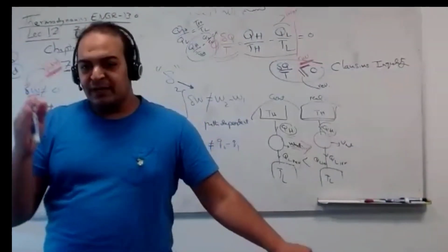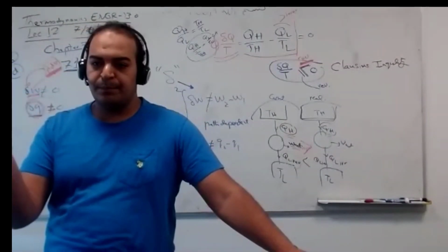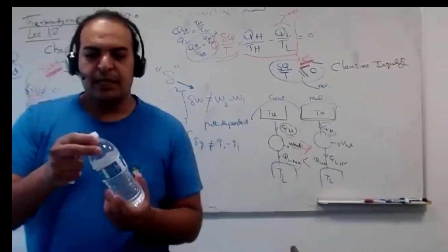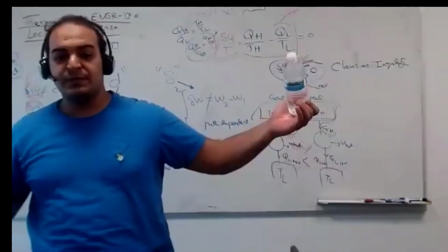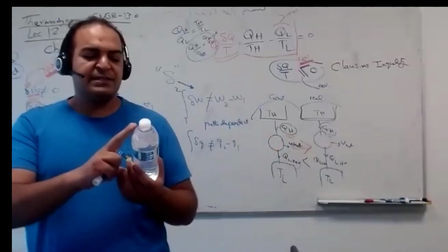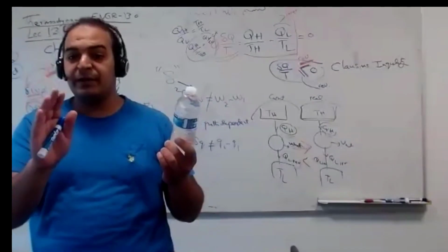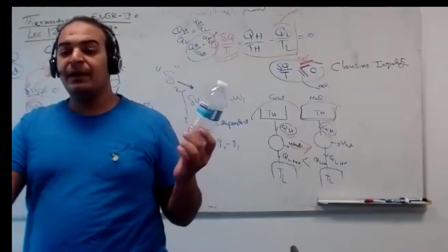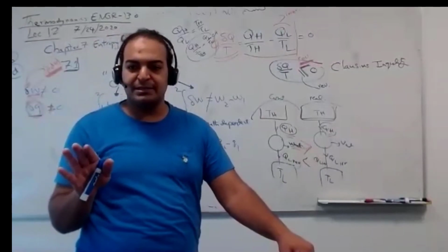The next column, which is VG, is 1.67 meter cube per kilogram. What is this? This water liter, if you heat it up until it becomes totally vapor, the volume becomes almost 2 meter cubes, 1.67 meter cube per kilogram. So this water in liquid phase is very small, 0.001 meter cube per kilogram. If you heat it up, it becomes completely vapor at the same pressure and the same temperature, 100, at a volume of 1.67. Correct, guys? Can you follow me, guys?